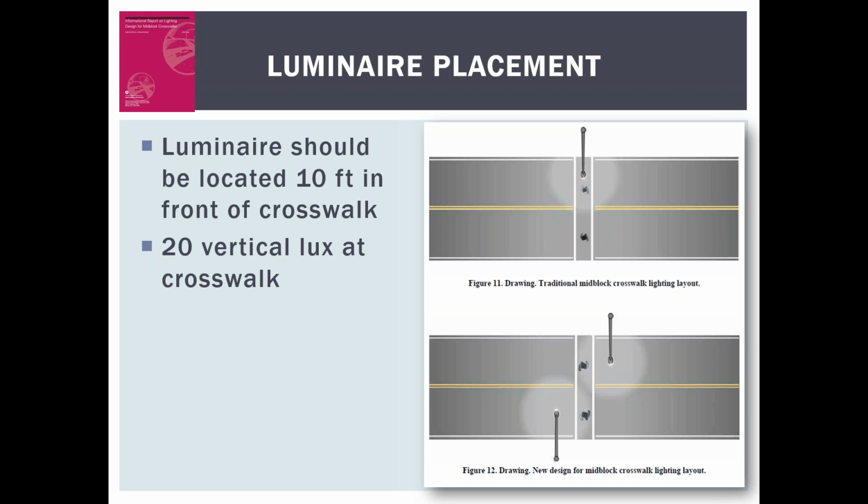Note that for roadways that have traffic traveling in both directions, particularly those without a center median, two luminaires are required, located on either side of the road and placed prior to the crosswalk from the driver's perspective.